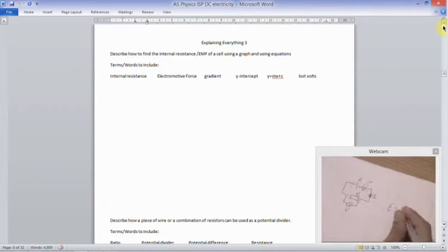So we can split these because we know that voltage is equal to current times resistance. So voltage is equal to current times load resistance here. That's big V. Little v is the lost volts, which must involve little r, so it's current times little r. There we go. We can bracket those up, or factorize them, so we've got that in a separate form. Or we could leave that as V, which is often given, and IR. That is the most common way in which this equation is written out.